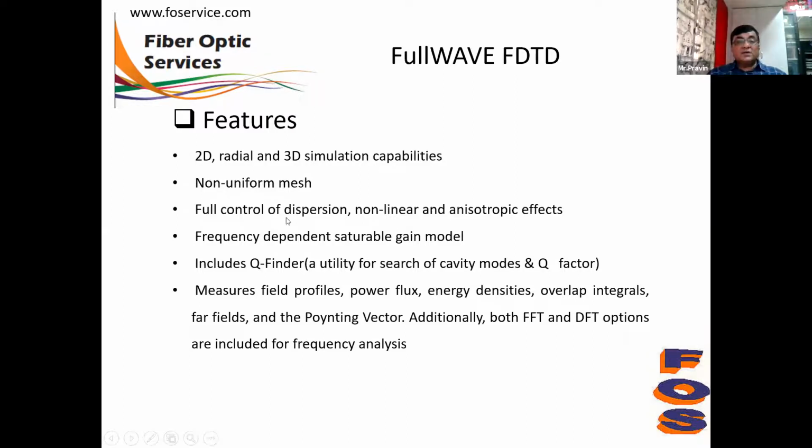It has full control of dispersion, nonlinear and anisotropic effects. It has a frequency dependent saturable gain model. Full wave FDTD also has a Q finder, which automatically finds the cavity modes and Q factor. It measures the field profile, power, flux, energy, and so on. It also has different frequency analysis options.